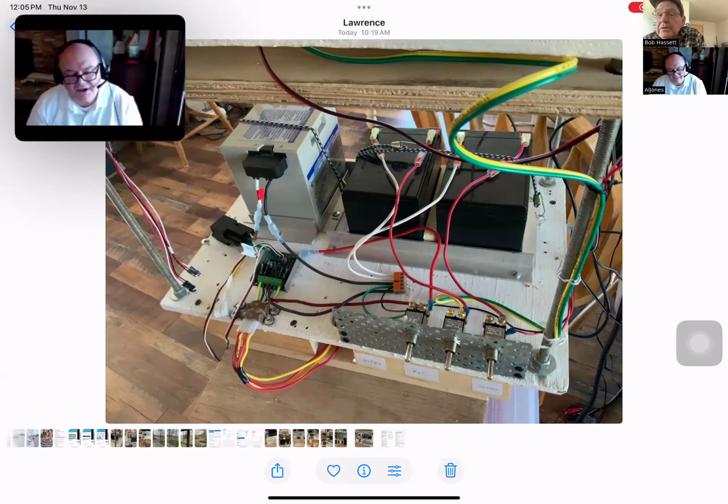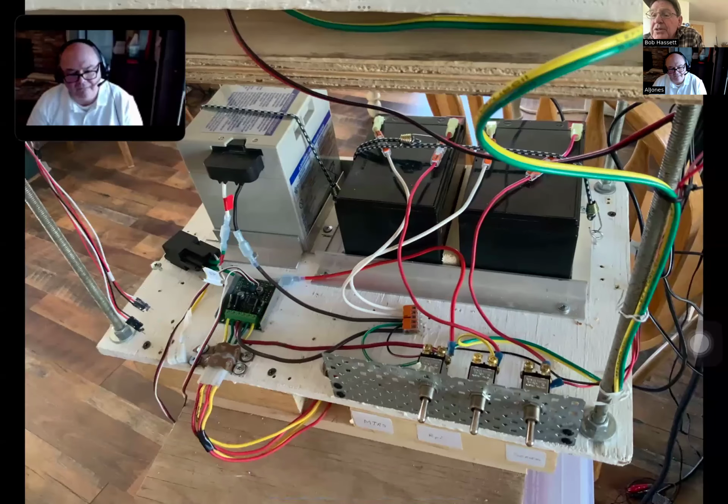Did you drill those out? Those are probably round, but you had some square holes. How did you get those square holes so nice and square? Well, the plate comes pre-formatted with squares and diamonds. So I picked one of the holes and started with a small drill bit, and then stepped up to different diameters, up to a 1/2 inch. There's lots of burrs, so I had to take a hammer and pound them down, and then wiggle the drill bit to clean them up. Nice.